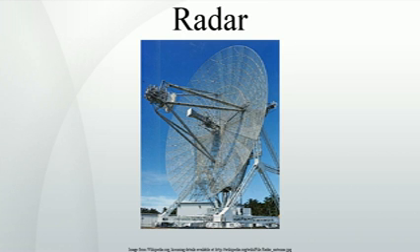The signal is then sent out from one antenna and received on another, typically located on the bottom of the aircraft, and the signal can be continuously compared using a simple beat frequency modulator that produces an audio frequency tone from the returned signal and a portion of the transmitted signal. Since the signal frequency is changing, by the time the signal returns to the aircraft the transmit frequency has changed. The amount of frequency shift is used to measure distance.